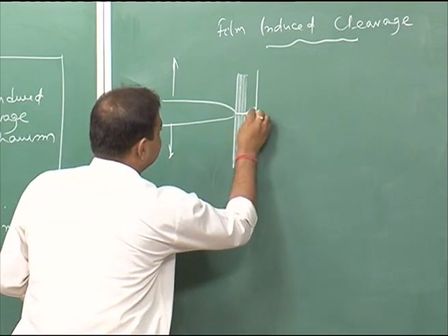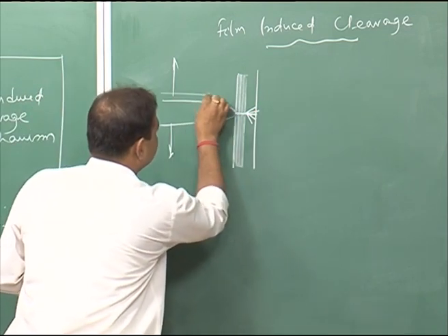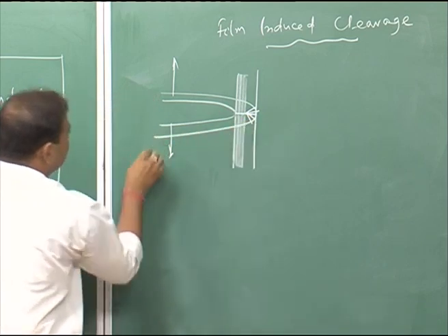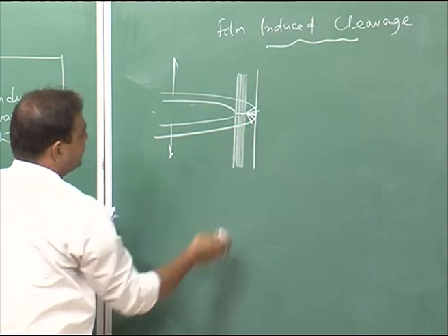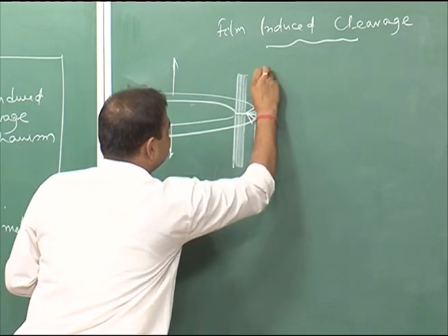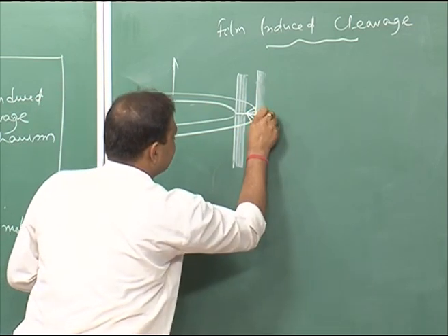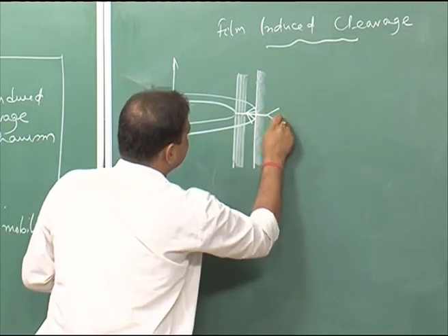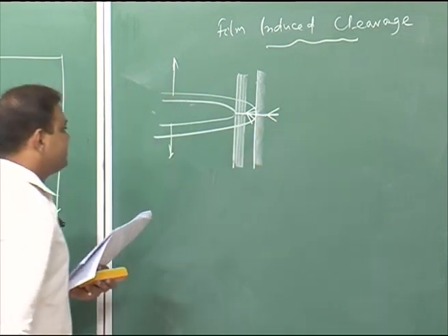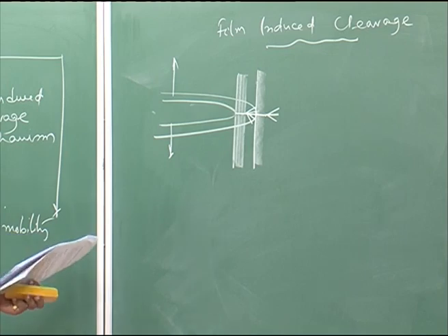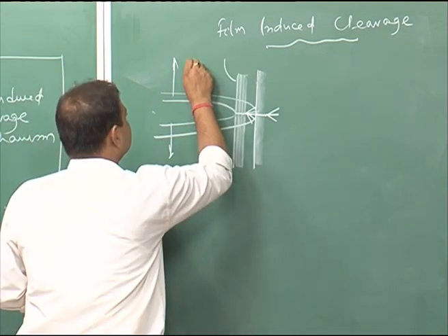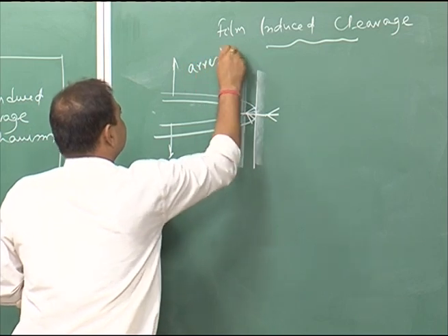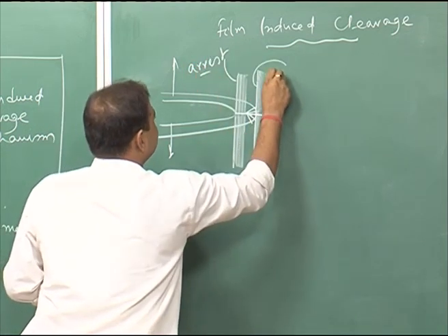So, then again here we have a little extra growth, and then this crack is growing like this, and again you have passive film formation. Then again this sharp crack is propagating, and then again it goes to the adjacent metallic volume. So, like that it moves on, and there you have a crack arrest mark. This zone is another crack arrest,